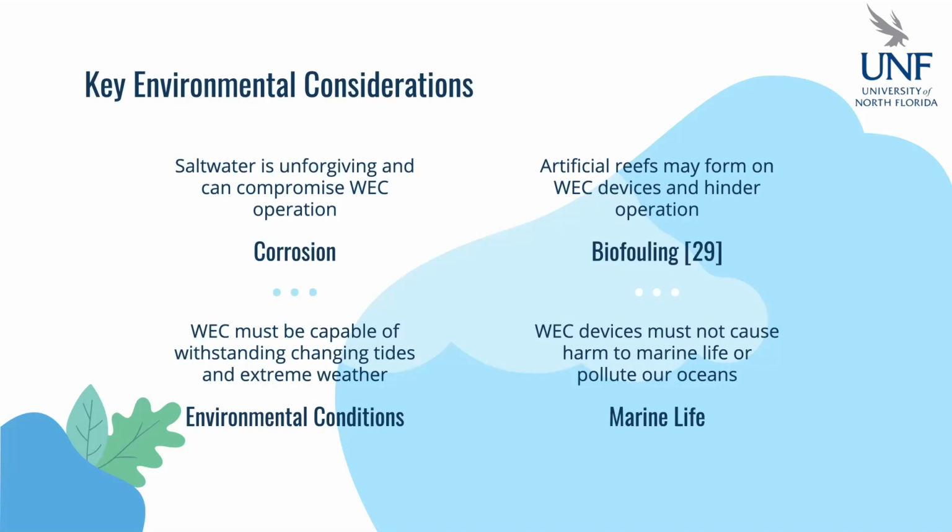Salt water is unforgiving and can compromise the WEC's operation. If part of the wave energy converter rusts out or disappears, we could have parts breaking off. We could have operation totally impaired. Biofouling, if artificial reefs start to grow on it, can hinder the operation of the WEC.